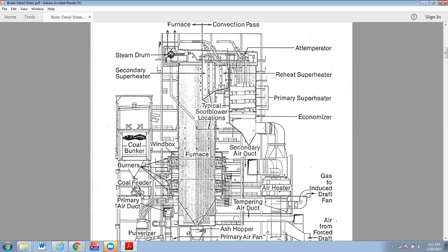We come down, we cut over and go through the rotary air heater, where we've got the blast of the combustion air coming in from the forced draft fan. On one side of this is the thing that rotates around, and half of it has the hot flue gas on one side, and the other half has the combustion air. There's all kinds of metal and heat transfer surface in there that gets hot and rotates around to the cold side. This thing just runs around in a circle.